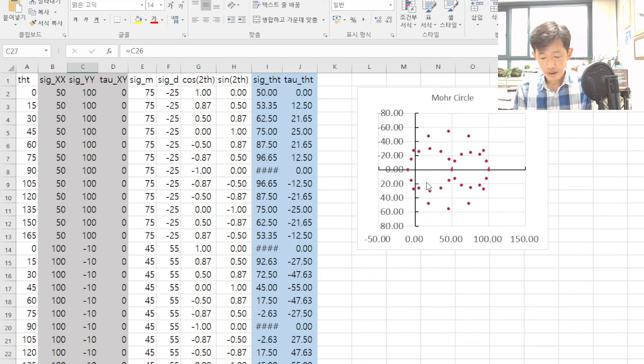And then here, before we talk about the example problem, let's talk about two different fabrication procedures to produce pipe. The first one is the helical welding procedure. The second one is the UOE welding procedure. In the case of the helical welding procedure, they wound the plate in the helical direction. Because of this procedure, we have a welding line.